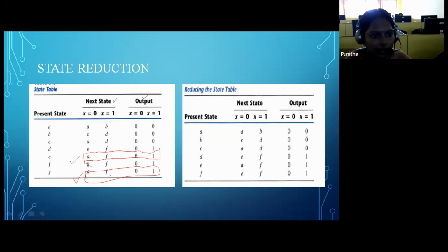Okay, these things are repeating. For this one, I need to eliminate any one of the states. What will I eliminate? The last one I eliminate, because they both have the same processing, right? Why do we need the same processing state repeated? So I'm deleting this whole line.